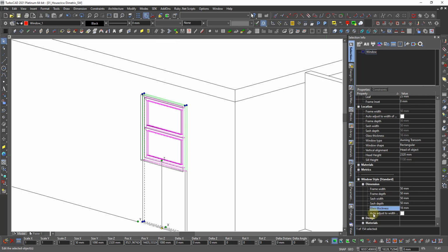I never use adjust to it, because then the window, the sash, will be in the middle of the wall, and it's only the frame that will go out. And that is a stupid way to make a window, if you ask me, because there will be a lot of water collecting here, and then the window won't finish. So I never use this one.